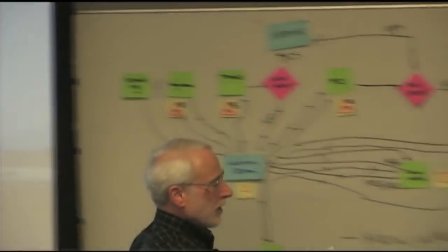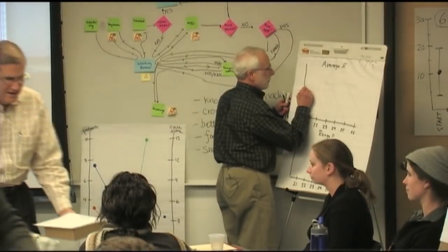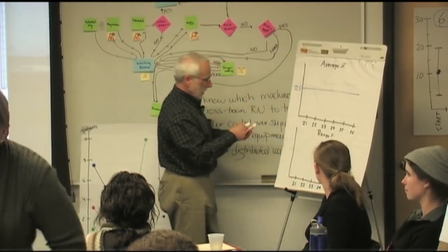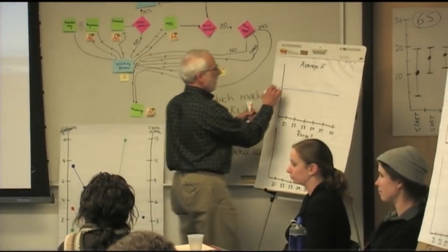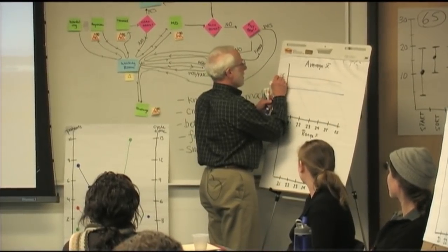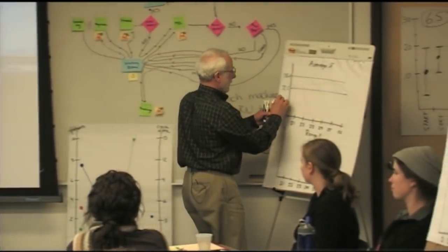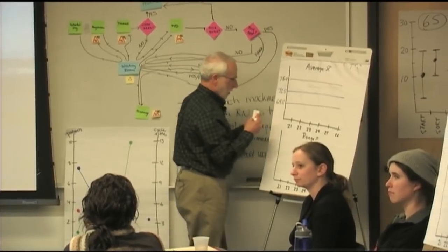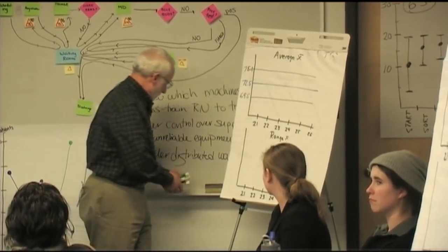We want to do something like this. First of all, let's get the mean. I'll just do one, and then I'll let the other tables do theirs. This is like 72.5. That's the mean. And then the upper control limit is about 75.4, so we'll put that here. And the lower control limit is 69.5. You're going to want to finish that. This is for the average and this is for the range, and I'll let each team finish their own.